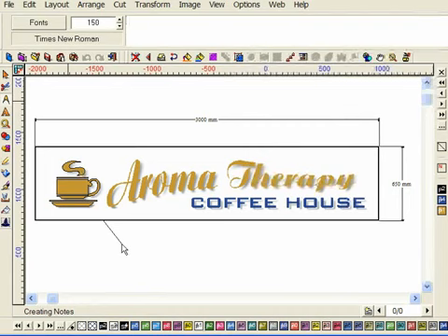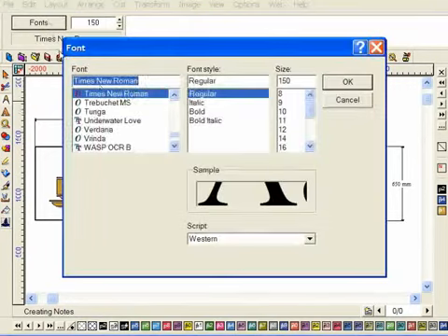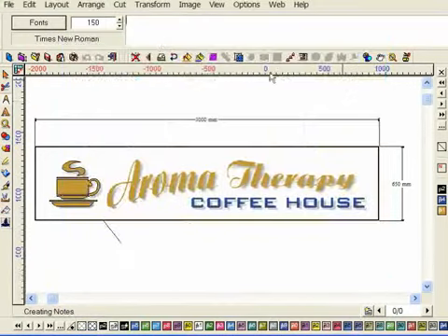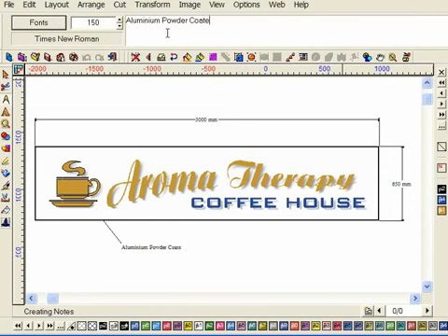Once I have done this, you'll notice that a dialog box appears in the taskbar, enabling me to enter my description of the frame. Like the Dimensions tool, I have the opportunity to change the font style and size to be used. I am happy with these settings, so I'm going to go ahead and type some notes in the dialog box. As I do this, you'll notice the text starts to appear on screen.